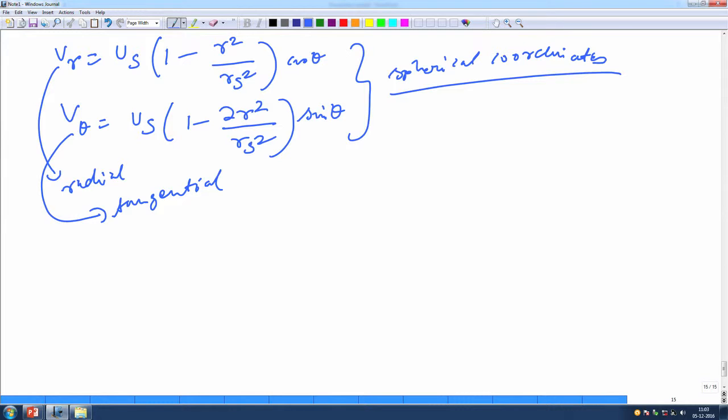We also assume that these velocities are by the way variable, okay, they are not constant, but we assume that the Hill spherical vortex applies to the unsteady situation also and during the vaporization of the droplet. The simple reason is that we already established that the vorticity transport happens in a much shorter time, and that is the reason why we can actually go by it, okay.